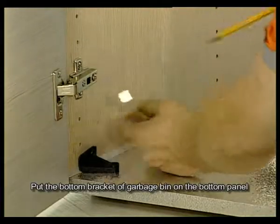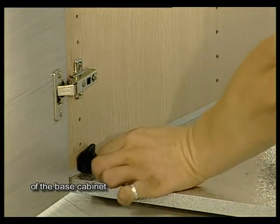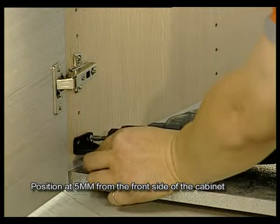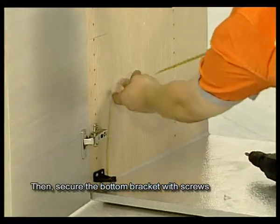Put the bottom bracket of garbage bin on the bottom panel of the base cabinet, positioned at 5 mm from the front side of the cabinet. Then secure the bottom bracket with screws.